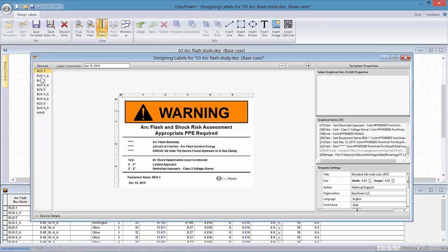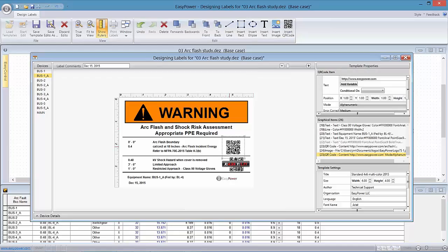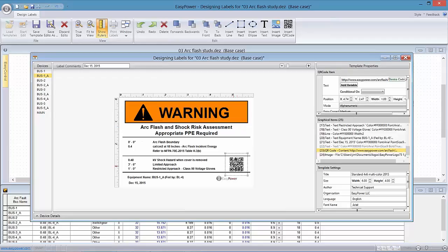Next thing I want to look at is how I can expand the information that's available, and that's where the QR code comes from. What we've done in this particular example is I've associated, and again, if I select the QR code, I put it in by selecting the QR code up here on the top right, put it in the location that I want it to reside, and then here is where I'll describe the properties of that particular element. So instead of putting another one in, I'm going to go back to the one I've been using, which is this one here.